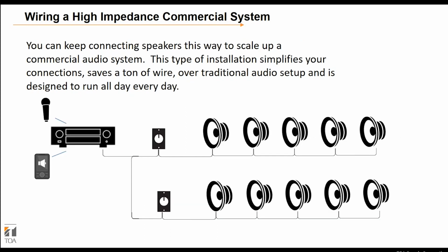You can also then keep connecting speakers this way to scale up your commercial audio system. As long as your amplifier has the power capacity to add more speakers on, you can add speakers to the line to your heart's content, and without really changing anything about how the system functions, the overall volume, et cetera. You're not changing the impedance on the line, so you're therefore not changing anything about how the speakers interact, except for adding more.